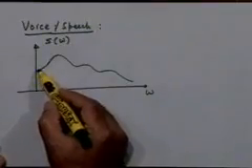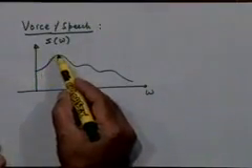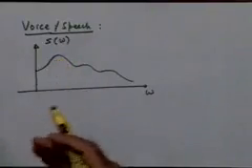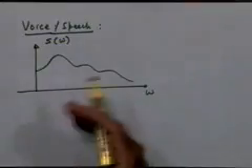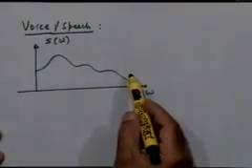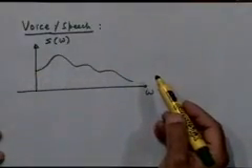Signal power as a function of frequency is typically the tool that you employ when you're talking about random signals. And if you model speech as a random signal, it's not really all that random, although there is randomness in it. The power spectrum builds up from slightly lower energy at the lowest frequency end to peak energy at about a few hundred hertz, which will vary from speaker to speaker and with the information that you are speaking. So this spectrum is not really fixed. This is just a typical plot that you might see.